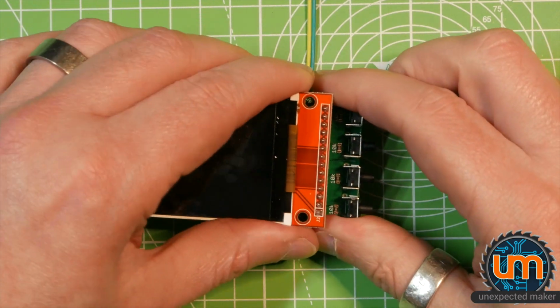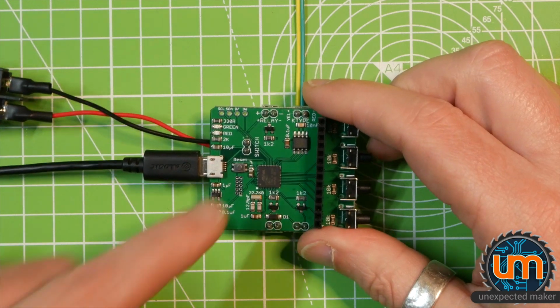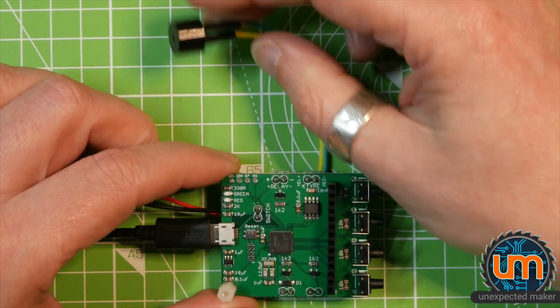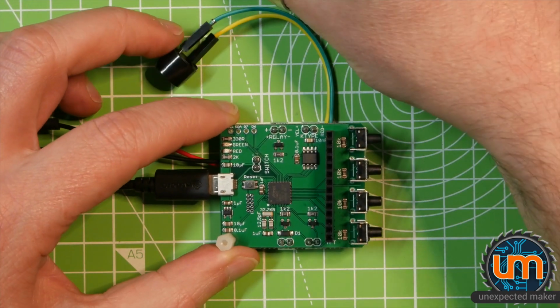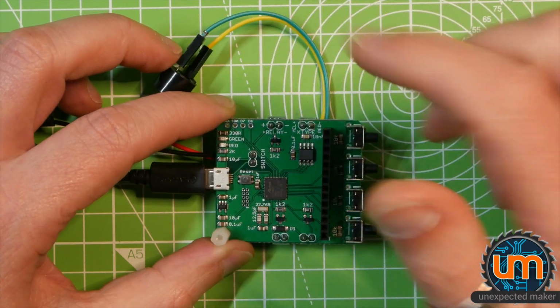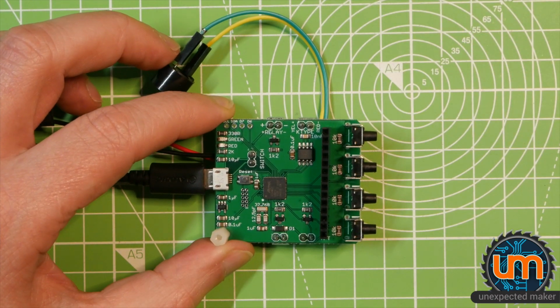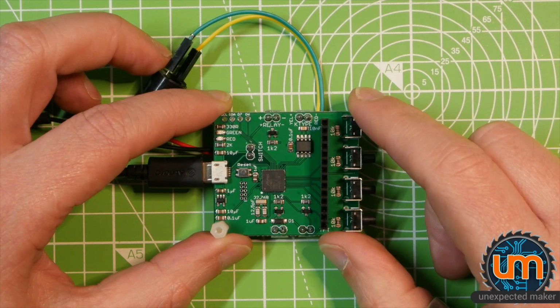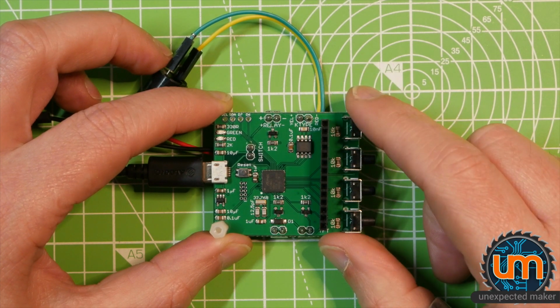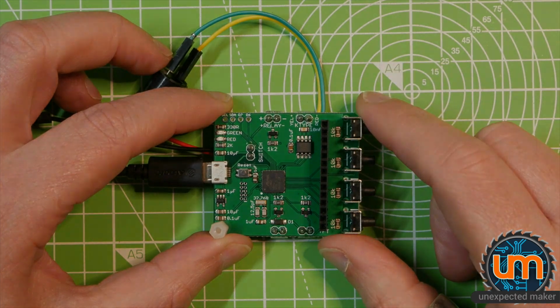What it is simply noise on the 5 volt line when the buzzer's going. If I turn the buzzer off in code so that no tone comes out, there's no problem. But if I leave it on, no matter what I set the frequency to, the screen turns off as soon as the buzzer goes. So let's have a look at the oscilloscope and see what's happening on the 5 volt line when the button's pushed and the buzzer goes.